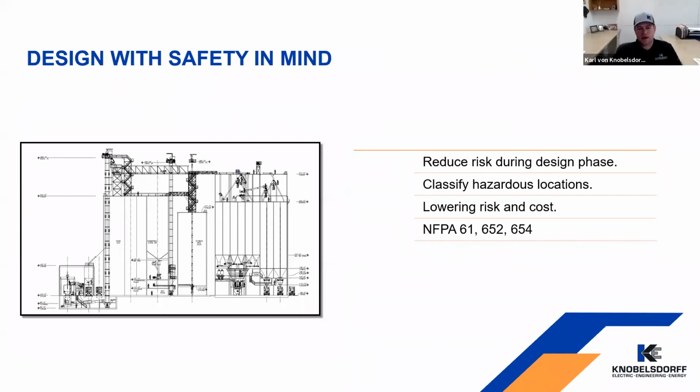All right, so when we're looking at design of a new facility or expansion, we're always looking at how to design the facility safely. We're working with another design build contractor that does feed mill or grain elevator or flour mill construction. Likely they're partnering with another third-party engineering firm, or they have those capabilities in-house. So we work with them. They're working on the facility design to comply with NFPA 61, 652, 654. And then we get involved once most of their design's done to figure out how we're going to apply all of the NEC codes and 499 stuff in that facility.